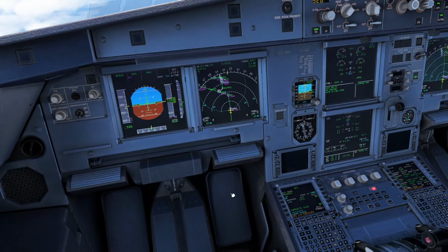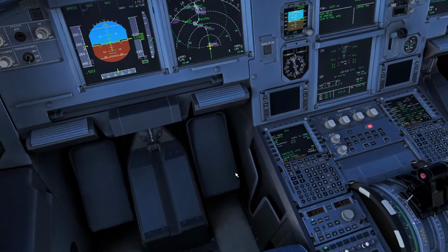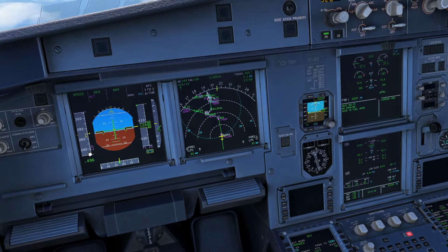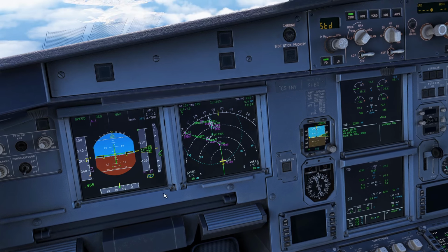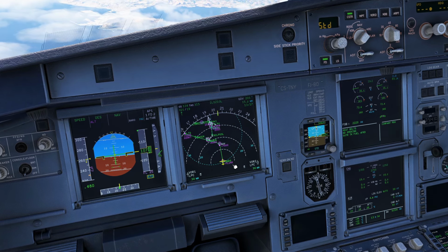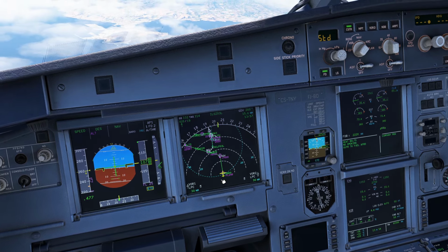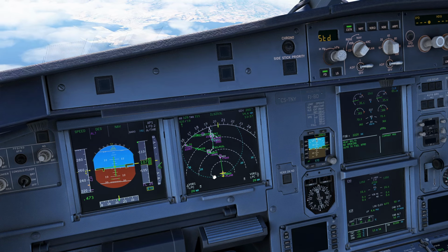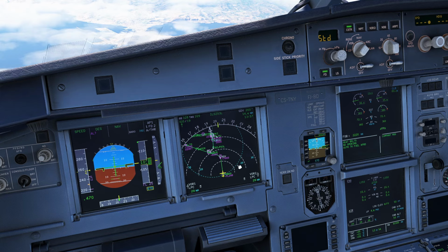We are just past flight level 110 and the speed limit of 240 was exceeded. 240 is here, and the aircraft started to reduce the speed to 240, and also just passing TUTCO at or below flight level 140, descending to Golf Delta Victor VOR at or above 7,000 feet.